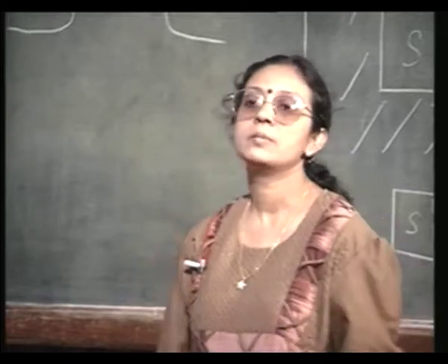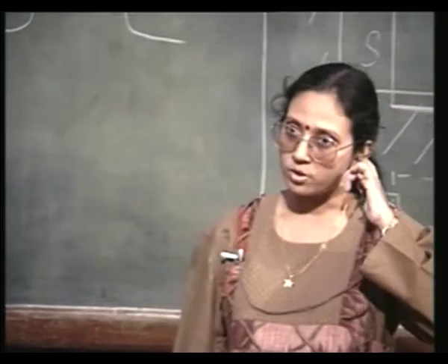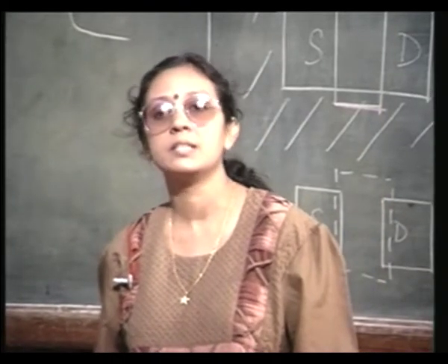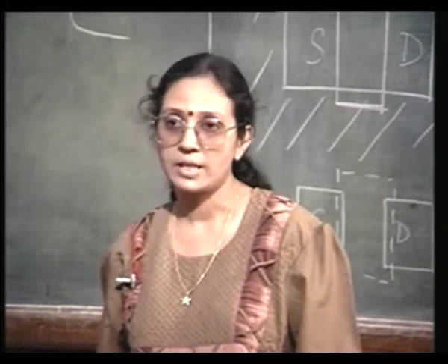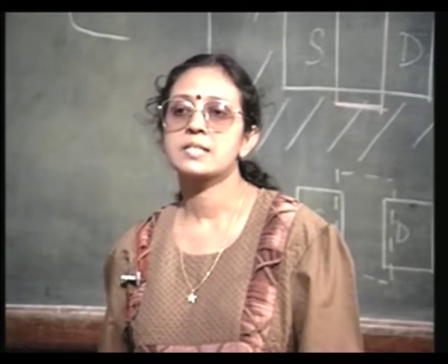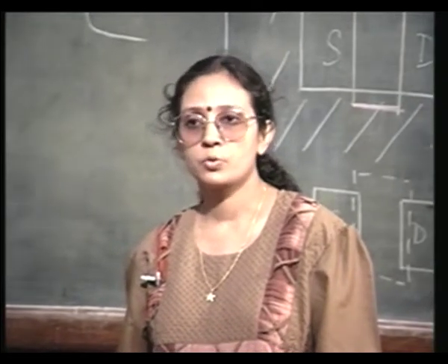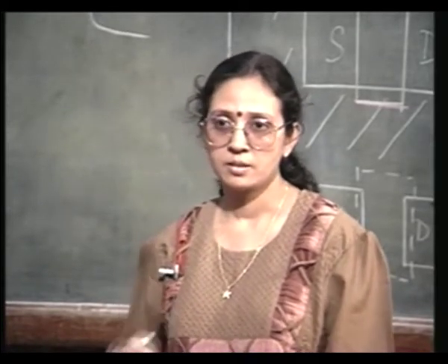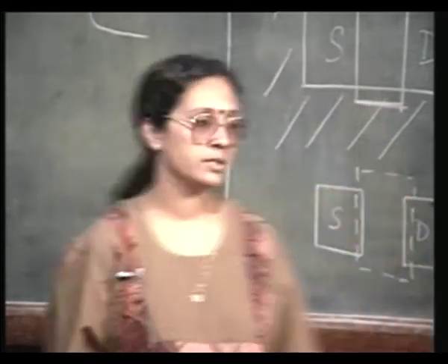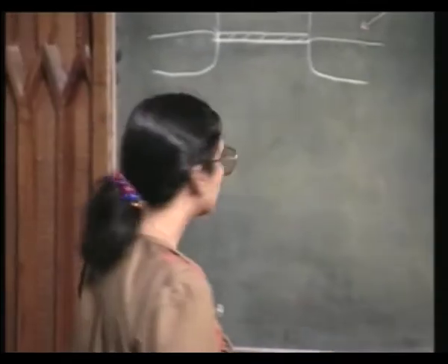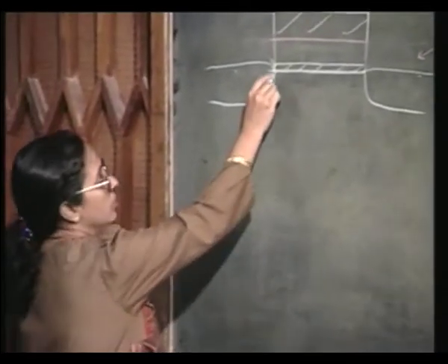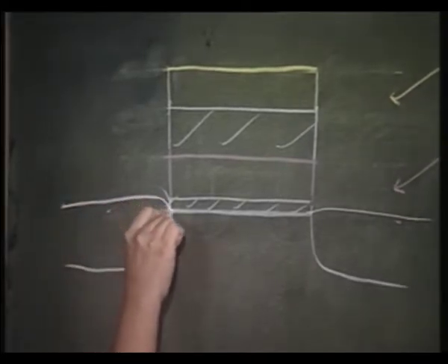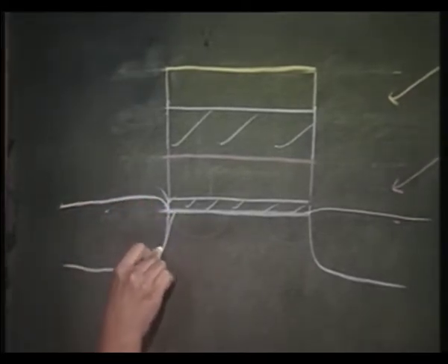The problem is simply this. We said that oxidation does not proceed underneath the silicon nitride, quite right, but there is a slight protrusion underneath. Okay, there is a slight movement inside. So, what you have is not exactly like this, what you have is a little bit of projection inside.